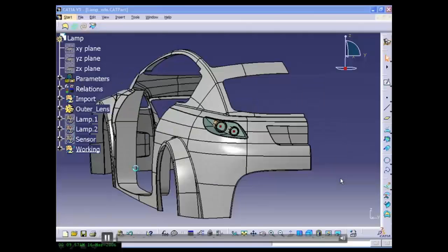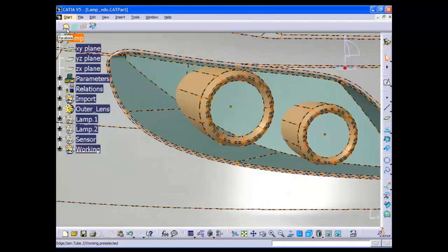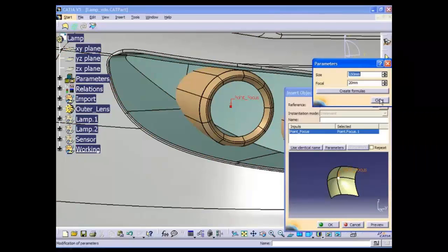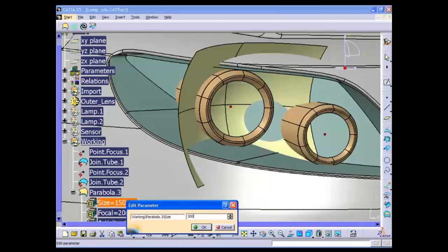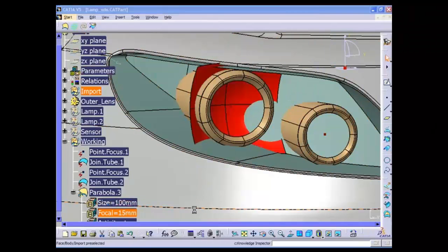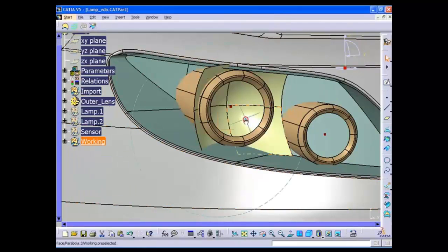Okay, let's begin the video. So we have a designer who needs to design the reflective lens for a taillight assembly. And to do this, you will first insert a geometric template of a predefined and fully parameterized parabolic surface with embedded Knowledgeware that will represent the shape of the reflective lens. And this is picked from a shared library of components.